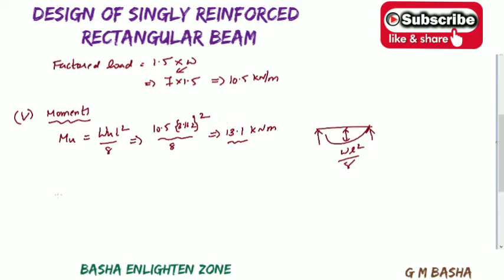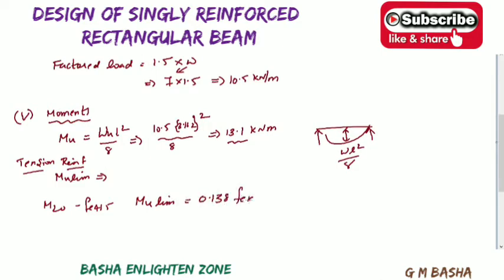Okay, then check the Mu limit also. This Mu limit will be based on the tension reinforcement. I already simplified all these things. Whenever M20 grade concrete and Fe415 steel are given, your Mu limit will be equal to 0.138 fck bd square. Please remember this formula directly.